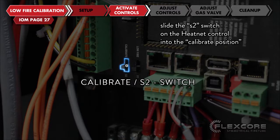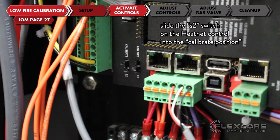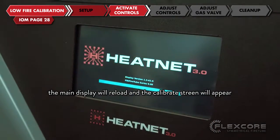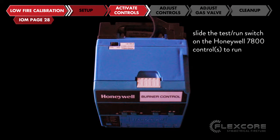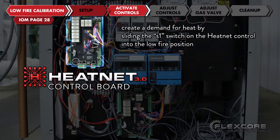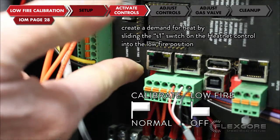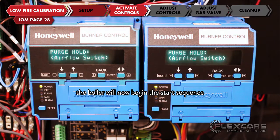Slide the S2 switch on the heat net control into the calibrate position. The main display will reload and the calibrate screen will appear. Slide the test run switch on the Honeywell 7800 control or controls to run. Create a demand for heat by sliding the S1 switch on the heat net control into the low fire position. The boiler will now begin the start sequence.